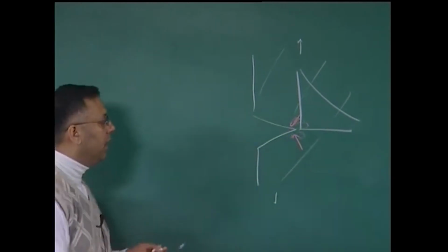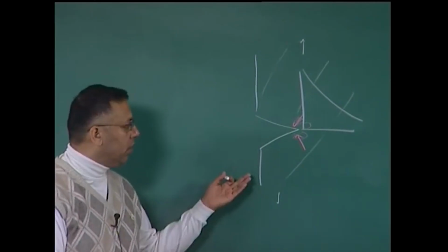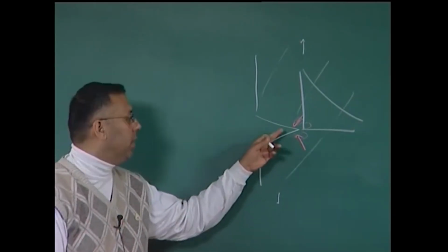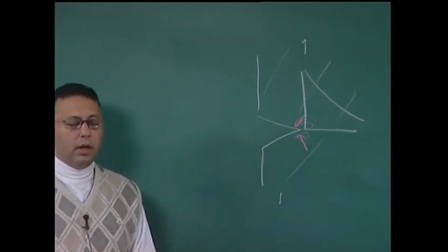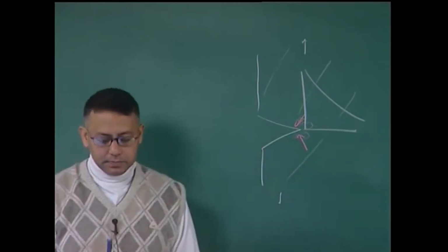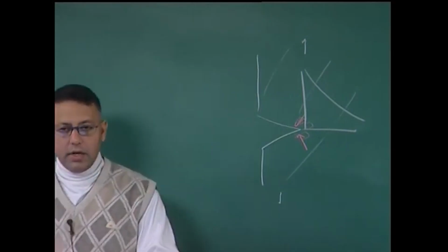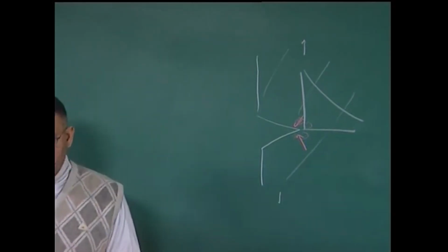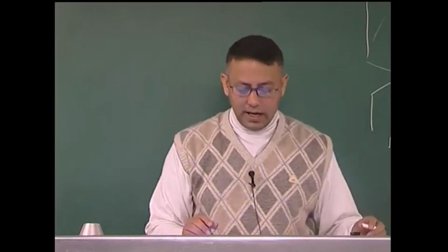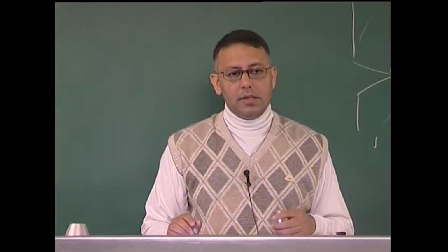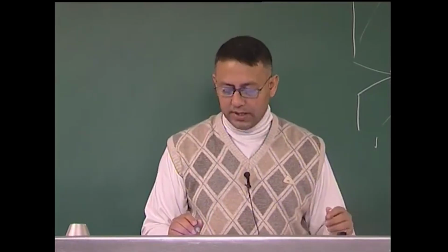Thus, what I observe is that this material actually gets toughened, because if there were no transformation toughening, zirconia being a brittle ceramic, the crack would propagate and lead to failure of the material. But because of this phase transformation, you can see that this is actually giving rise to toughening of the material. So, this is some kind of a secondary effect coming from crack tip stresses, but a direct effect is the next one which we are going to consider, which is the example of toughened glass. Okay. So, we know that glass is an amorphous material, and here we are talking about silicate glass, the normal glasses which we have in window panes, etc.